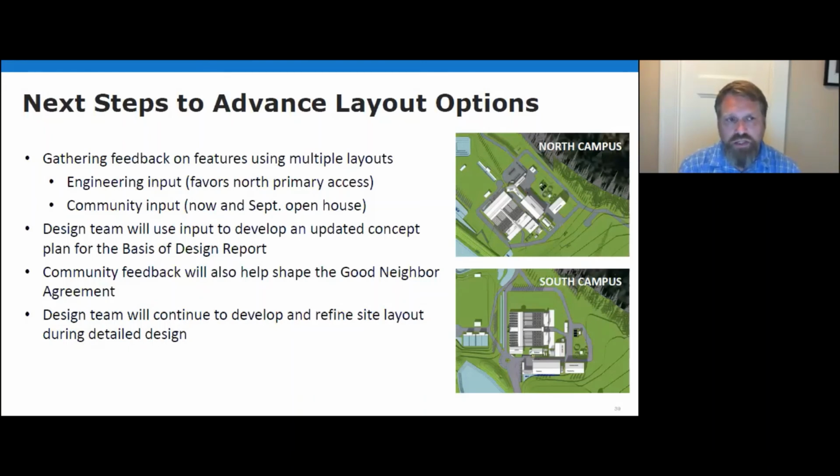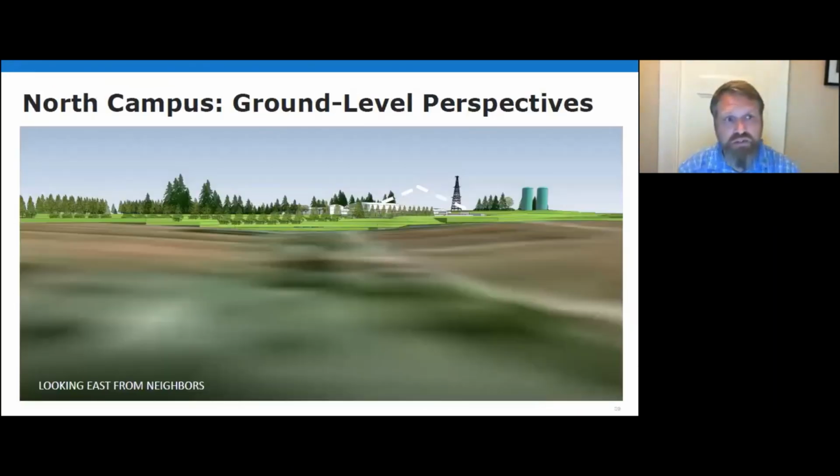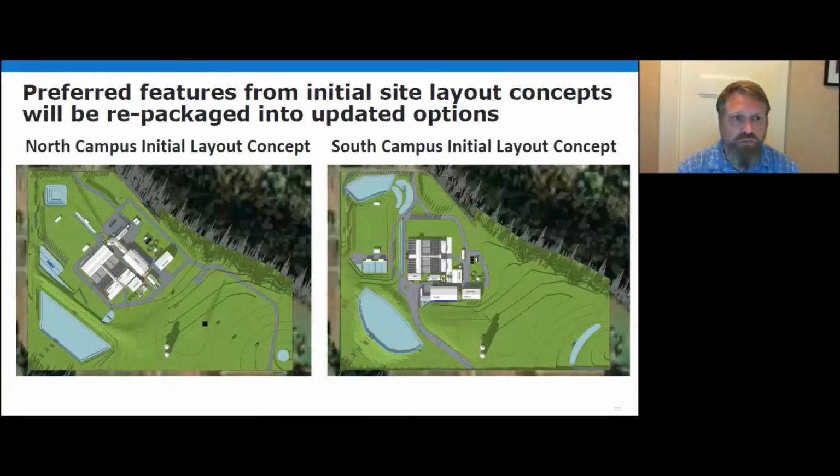Then our plan is to use those swales to direct the stormwater to more intermediate facilities to be held and treated before, in large events, finally being shifted down to those larger stormwater ponds shown at the lower portions of the site. So we are going to try to capture and treat as much as possible, as close to the source as possible.